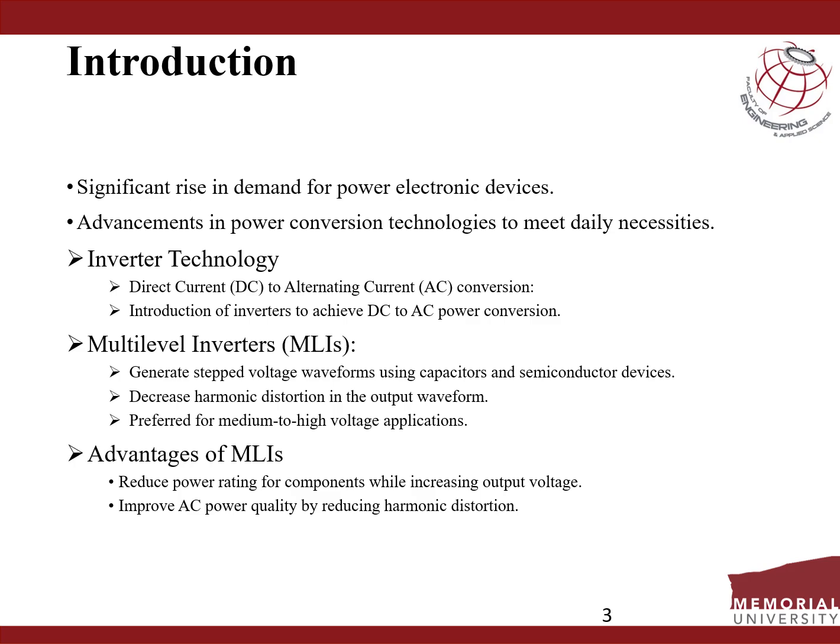Among various multi-level inverter topologies, the Cascade H-Bridge inverter stands out due to its simplified design and efficiency, requiring fewer components to achieve the desired voltage levels with low total harmonic distortion, which is also known as THD, and it also reduces the switching losses.